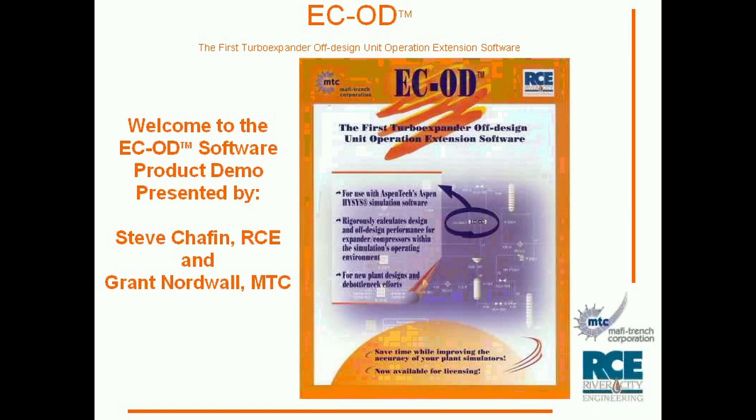ECOD is the first unit operation for AspenTech's HYSYS simulation environment written specifically for modeling a turboexpander compressor. ECOD rigorously calculates design and off-design performance for an expander compressor within the HYSYS environment. ECOD can be used for rating studies of existing equipment, off-design calculations for expanders during the plant design phase, and what-if studies for new processes.